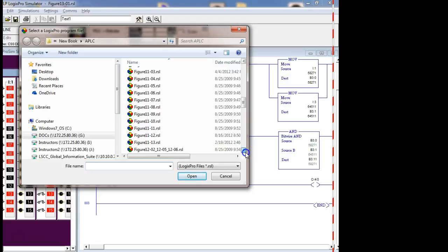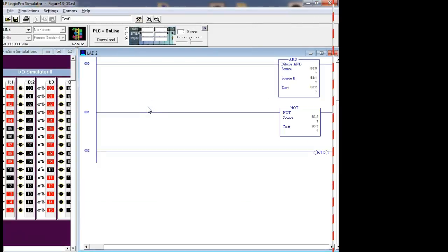So if we wanted to do a NAND, what would we do? ANDs and ORs are considered to be outputs. I know I told you that wrong at the start of class. Notice here they're taking D30 AND D31, storing the destination in D32, and then they're taking D32, NOTting it, and sending it back to D33. And this performs what type of operation? A NAND. Whatever comes out of the AND is inverted.